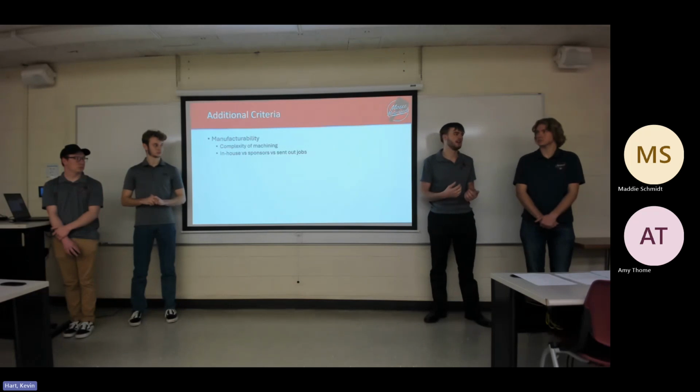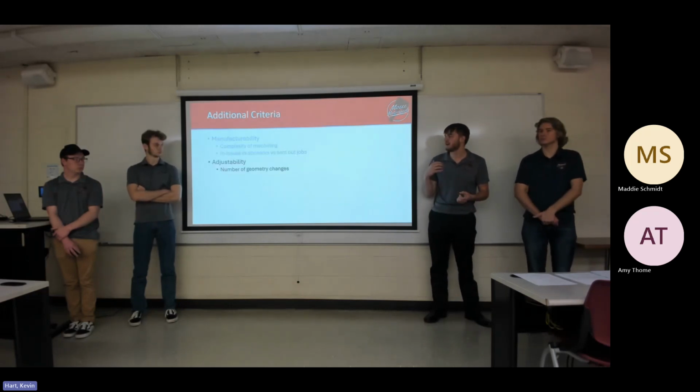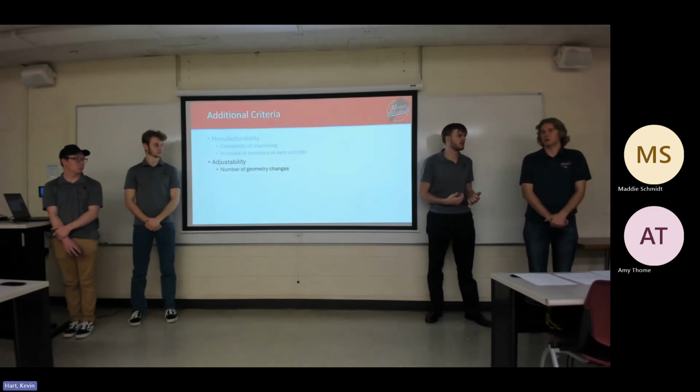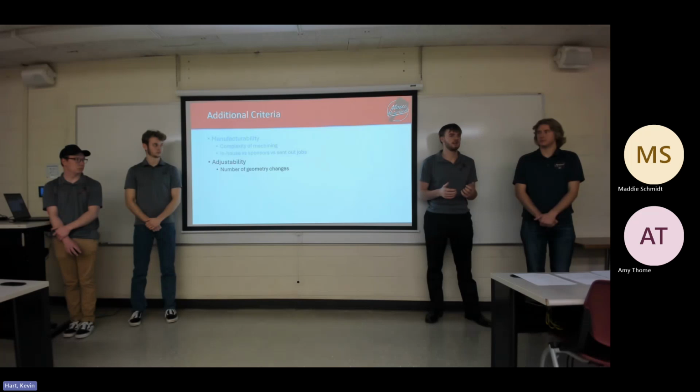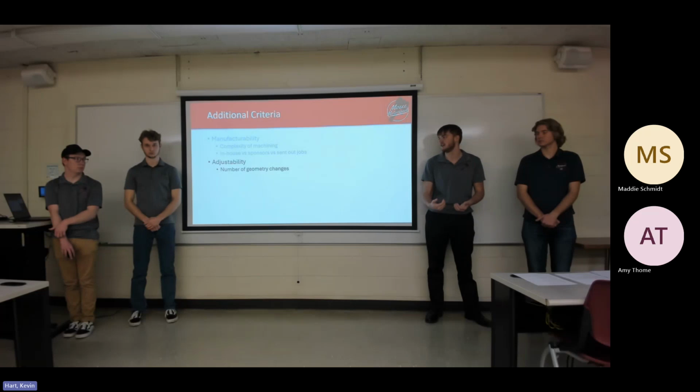So the more we are able to make in-house and the faster we can make it, the better it is for our timeline. The next we looked at was our adjustability. We are not modeling any transients in our suspension and our simulations, so being able to change things such as toe, camber, caster, our overall motion ratio, our spring rates, and our damping ratios very quickly. This is something that we'll be able to do to get the most out of our short amount of testing time that we get with this vehicle.